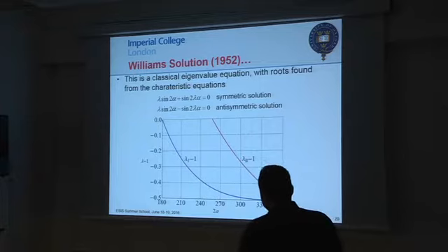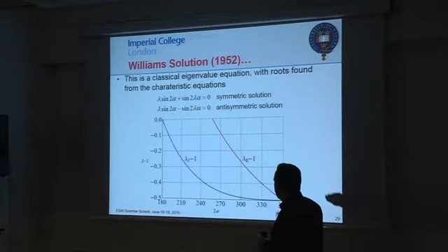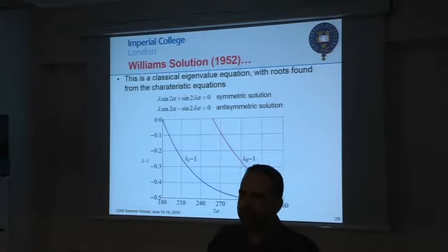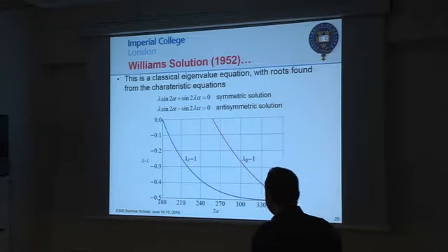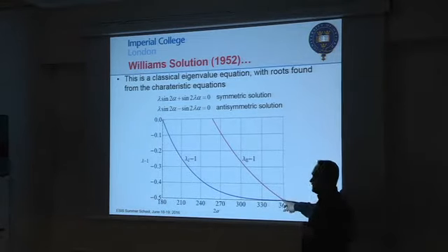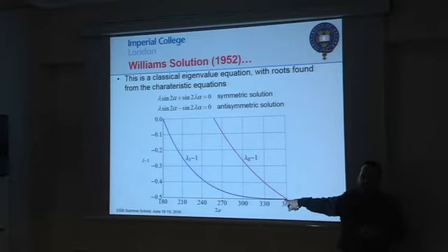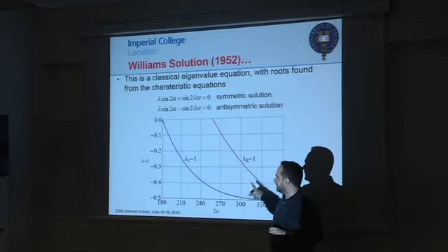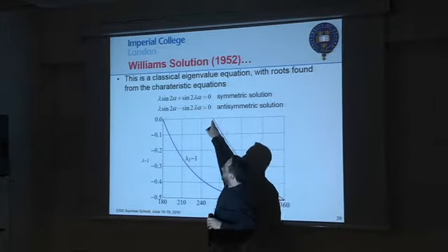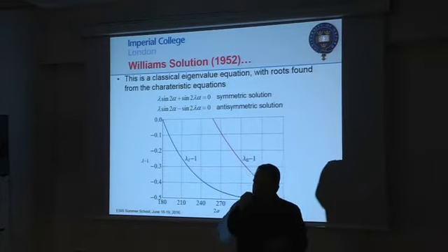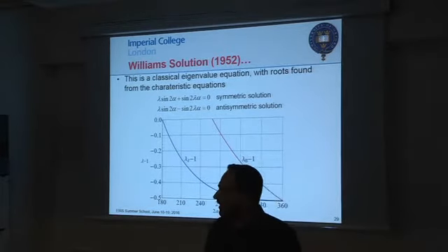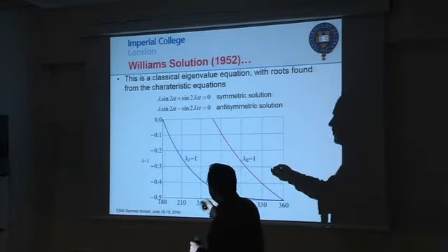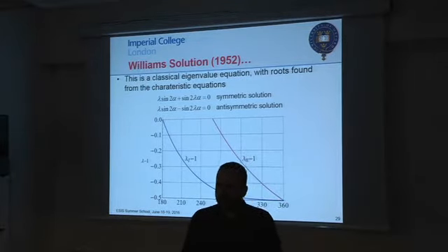Now for mode 2, when you solve the other equation, you get the exponent of your power law function, r to the lambda 2 minus 1. The lambda 2 minus 1 exponent is singular, the same singularity as we know for a crack, but then it's weaker, it's not as singular as the other one. Up to a point, this angle is about 254 degrees. Beyond which, if you keep expanding the notch, the solution is not singular anymore.